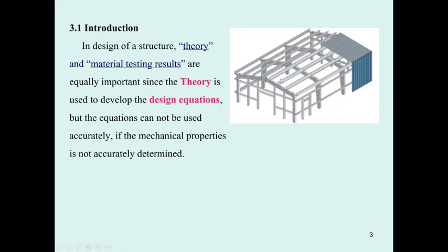If you consider the purlin on the top of this steel building, by the theory of structure, you may see that the weight of the roof sheet and the weight of the beam is going to be the dead load, and the live load from the wind or the rain is going to transfer to the purlin, and the force transferred along the purlin may be a uniformly distributed load.